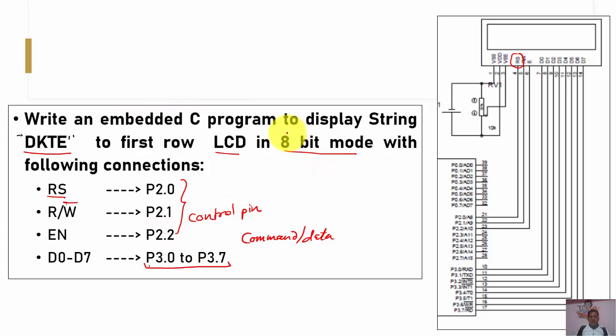As mentioned, we have to make use of the 8-bit mode. The first command that we are going to use is 0x38. It is going to initialize the 8-bit mode for the 16 by 2 LCD. No doubt there are many different commands for this LCD, which we will find in the datasheet associated with it. But out of these, the most commonly followed sequence is this. Step 1 is to initialize the LCD.